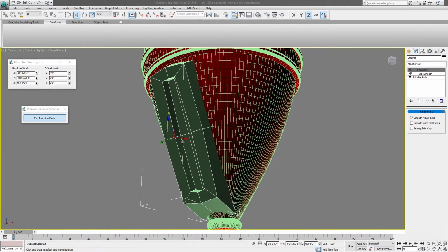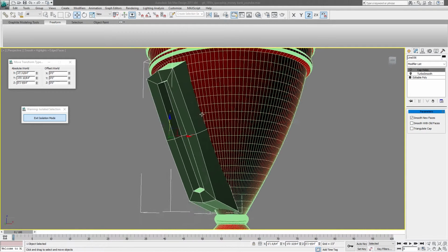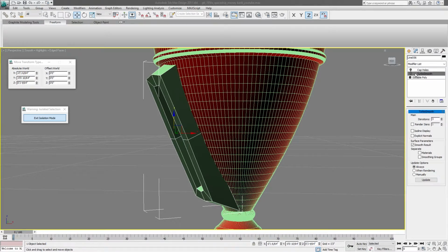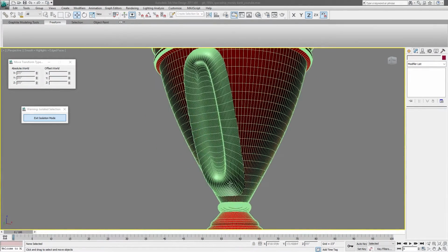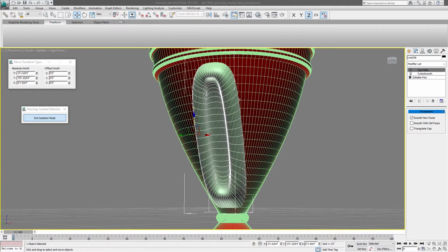But that's great, because this is supposed to be the base geometry for something we're working on later. So if you take this editable poly and add a turbo smooth modifier, what that does is it smooths out all the edges using this really nice algorithm, which will give you kind of curved edges, smooth out your model, but also it allows you to retain the original object.